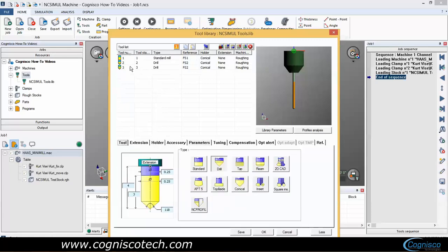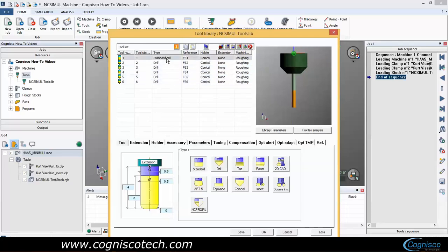If I didn't want to go through that and having to change the tool station, what I could have done is made this my default tool. So I click on this button up here so that now every tool I add is identical to that tool. If I go up here to my mill, make that my default tool, and I add a new one, well, my next tool is going to be my mill. So if you're creating a specific type of holder or a specific tool that you didn't want to restart from scratch, doing the default tool and adding a new one saves you some time.